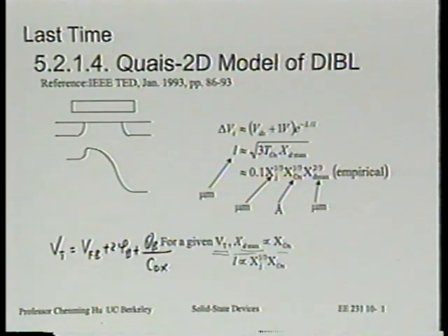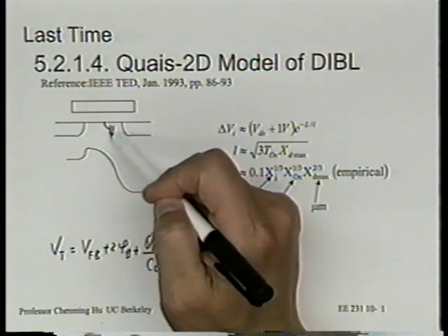So if you take from this the conclusion that it's very important to scale down oxide thickness, that's a very good message. You do keep hearing that it's very important to scale down the junction depths as well. Nothing wrong with it. But quantitatively, it's not as beneficial to reduce the junction depths as opposed to reducing oxide thickness. So oxide thickness will be our first weapon, but thinner junctions are always helpful. At this point, I'll point out this is perhaps a little non-intuitive, and this could be the danger of taking this model at its face value.